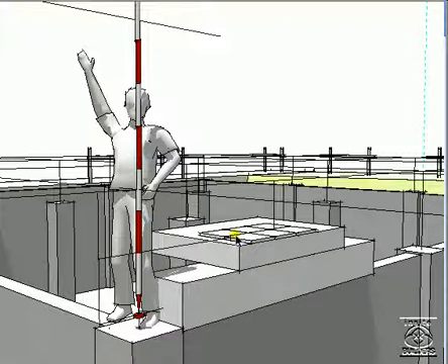From that 18 inches, we work down the total thickness of the tile, the slab, and the beam. That's 1 inch for tile, 8 inches for the slab, and 14 inches for the beam. So we have 23 inches down to the bottom of the beam from the top of the floor, which means the difference between this reference elevation and the bottom of the beam is 5 inches. 18 here, 23 down.